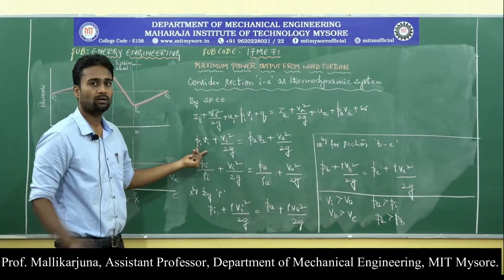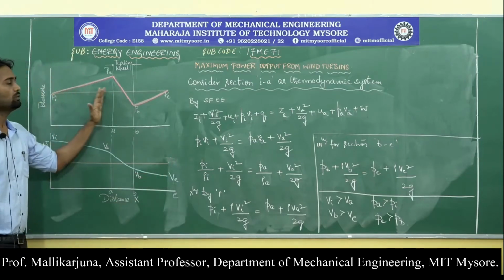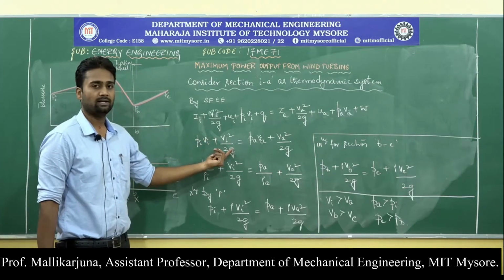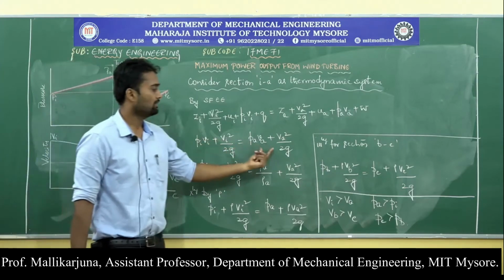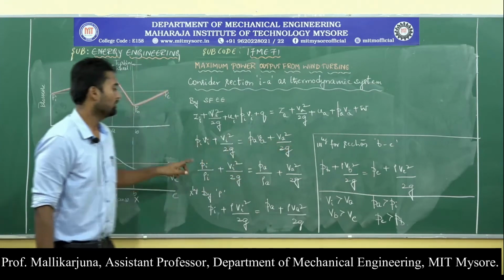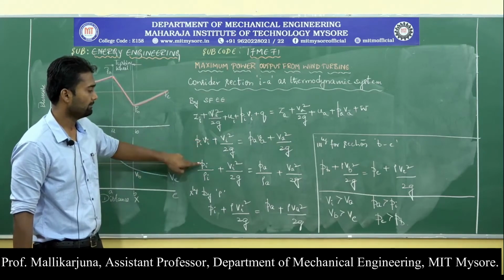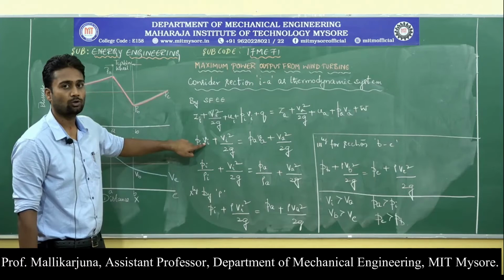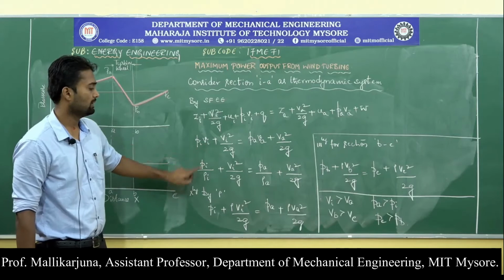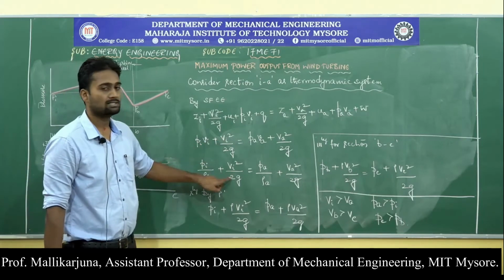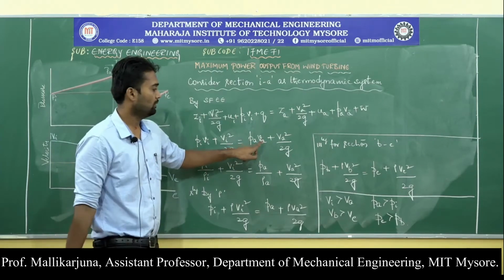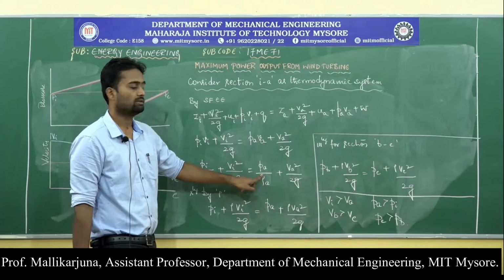This is nothing but the flow work, because the wind is blowing towards the windmill or turbine wheel. That is flow work, and the kinetic energy at the inlet portion and at the outlet section, which is nothing but flow work and kinetic energy. Now if I alter the equation, Pi I kept as it is. V is nothing but the specific volume, 1 by rho. So Pi by rho I have kept this term as it is, kinetic energy, and again here also Va specific volume at the outlet section, 1 by rho A is nothing but Va, I have substituted that over here.